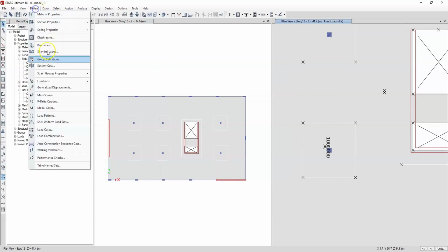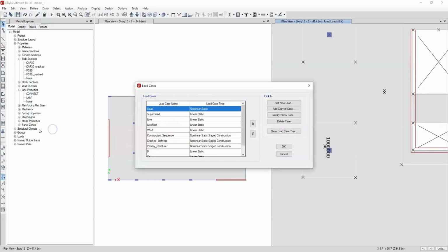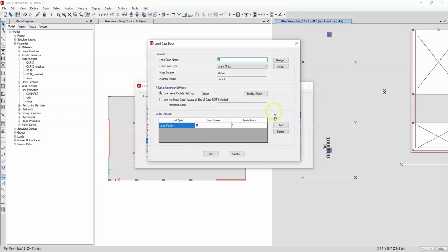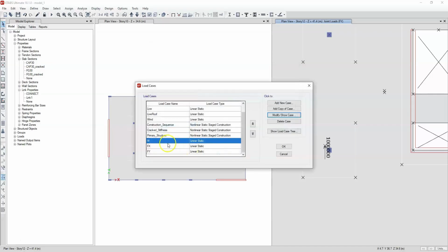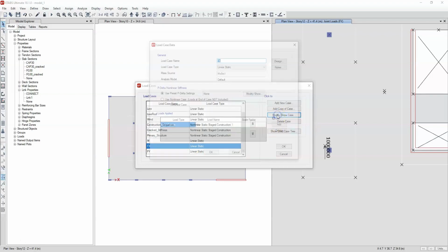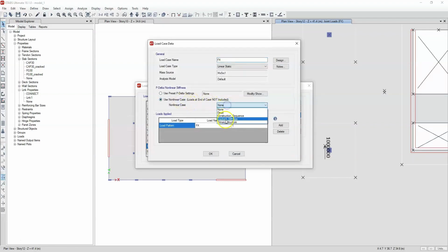It is important to mention that the three forces are going to be applied to a cracked structure. In the model, which is the model we consider to be one of the initially defined submodels, where we had three possibilities. The construction sequence possibility to calculate the dead load of the structure sequentially, the cracked stiffness which was the global seismic model with the entire structure cracked at 50%, and the model with the primary elements. What we intend to do is classify the global structure. For now, we use the cracked structure that has the entire primary and secondary structure at 50% stiffness.